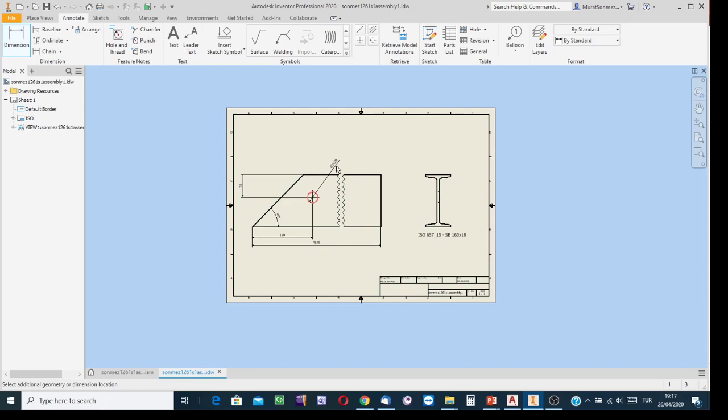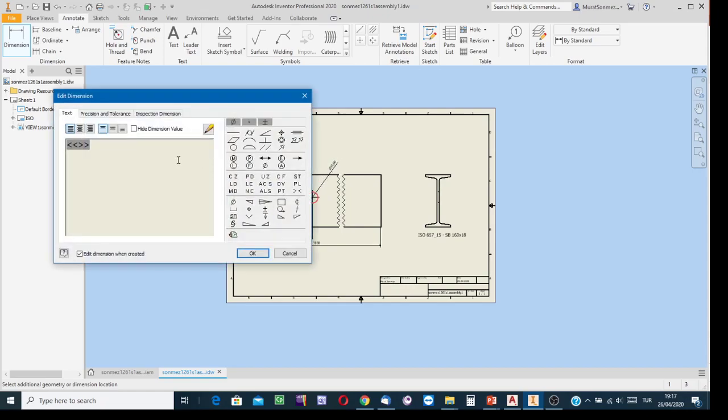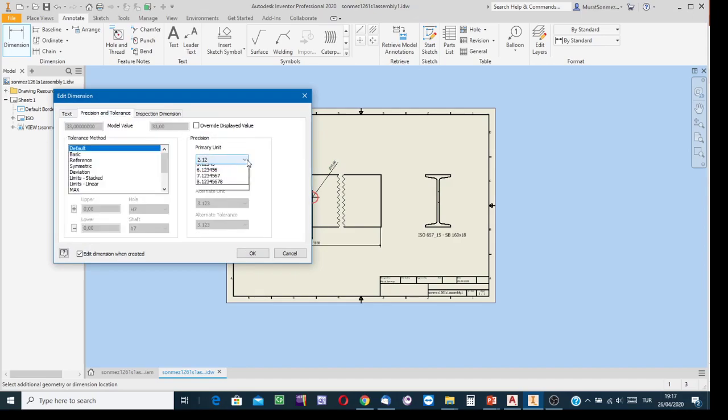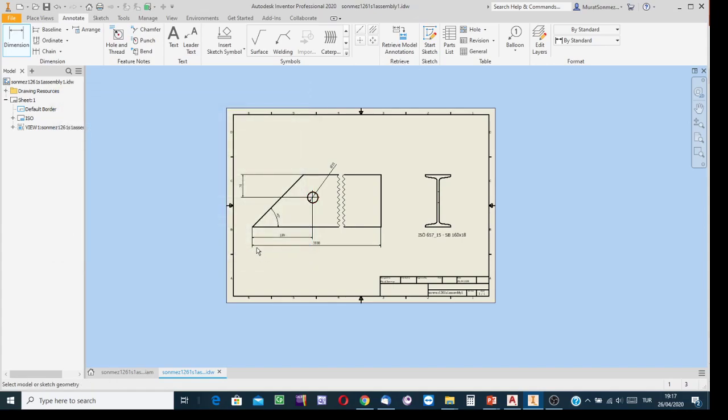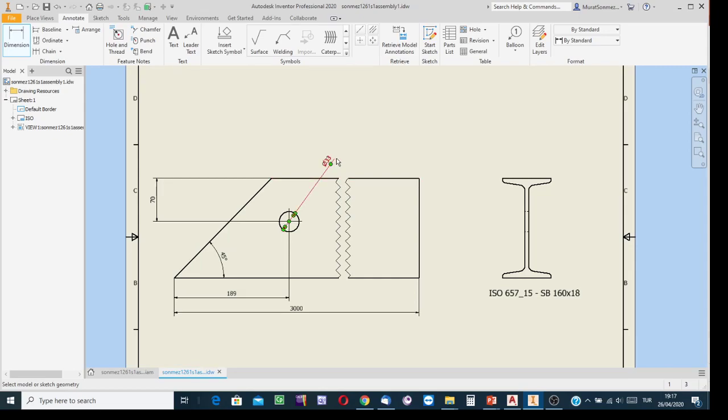I'm going to show the diameter rather than writing such a technical note. And of course, precision is to be 0. I know the geometrical tolerance zone, size tolerance zone, size tolerance class letter, geometrical tolerance class letter. So for size dimensions, I am sure precision is 0 and the nominal values are to be shown to their integer parts. But here, to inform the reader on all of the things about its geometry at the cross section, this specification note is valuable.